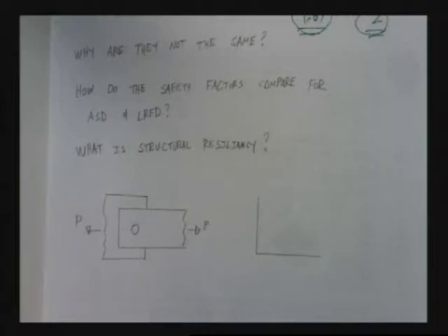That's right. It's the ability for other components of the system to help out and take some of the load. This idea that just because one aspect of our system is overloaded doesn't mean we reach failure. Well, we've got to be very careful when we say overloaded. If we're overloading something that has the ability to yield and give, then that's okay. If we overload something that's brittle, that's going to fracture, that's not okay. So it's this concept or idea that